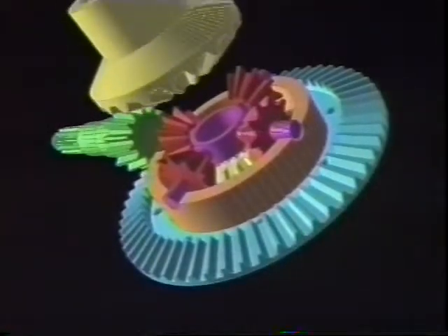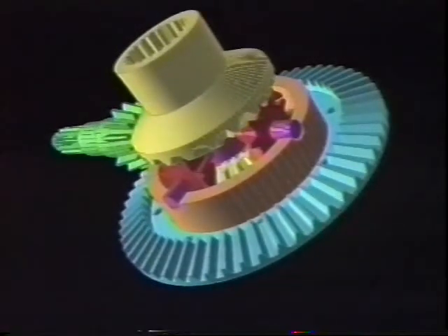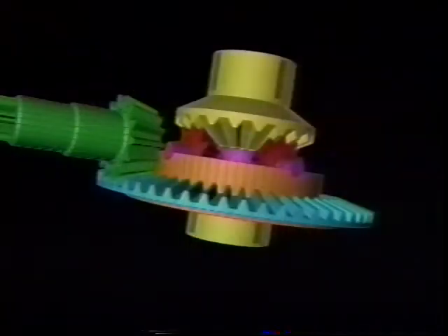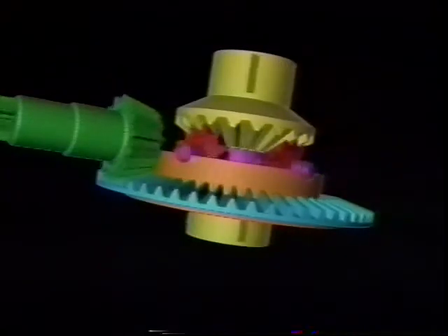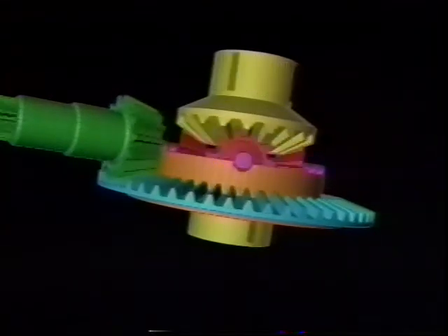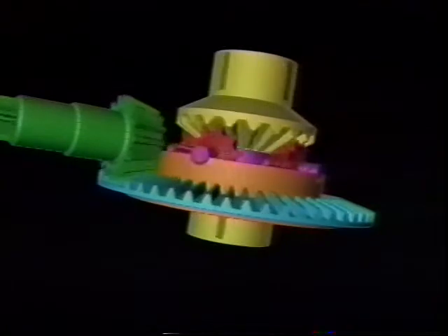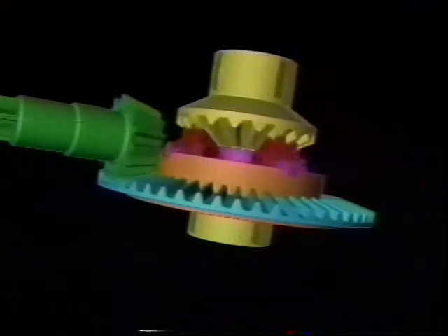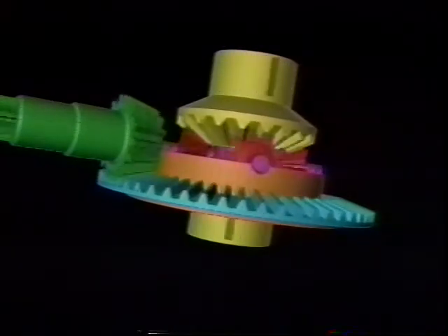The side gears are attached to the axle shafts and must turn at the same speed as the wheel they're attached to. Since the side gears contact the pinion cross gears when they rotate at different speeds, it causes the pinion cross gears to rotate on their own axis. The gear assembly no longer turns as a complete unit as it did when both wheels were traveling at the same speed.